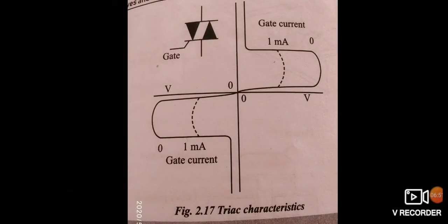Now, the figure shows the type of effect that occurs when an alternating voltage is applied across a thyristor or a triac. Forward breakdown occurs when the voltage reaches the breakdown value, then the voltage across the device remains low.